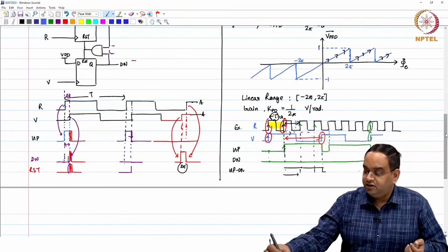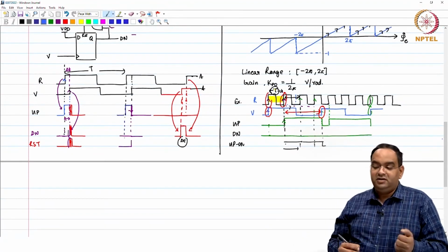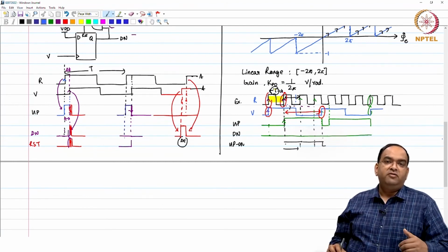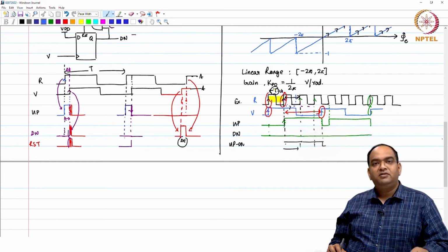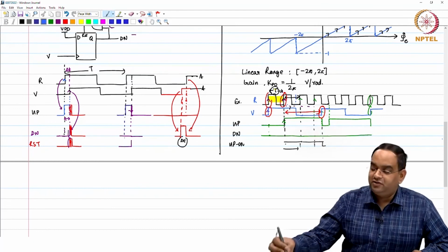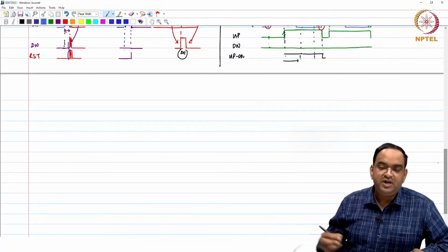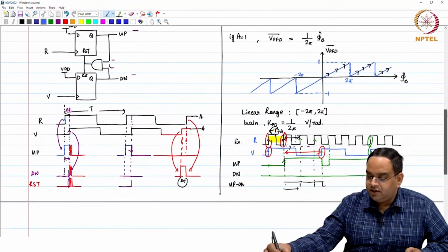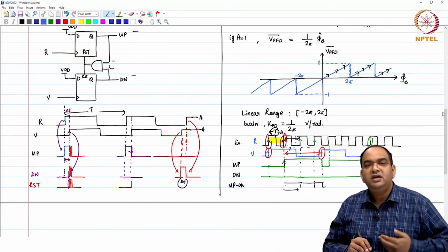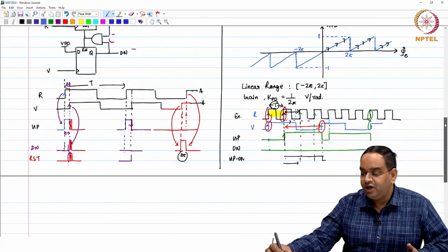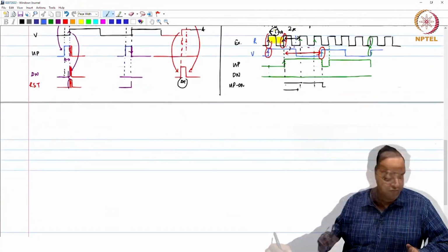So, this is useful for us to employ as a PFD, and do not worry about whether the phase detector will detect the frequency error in the given time and correct, and the PLL will lock. Well, those problems do not arise here. So, here what you see is, if you employ this PFD in your PLL loop, it will detect the frequency error and always change the frequency in the correct direction. So, that is about the phase frequency detector.